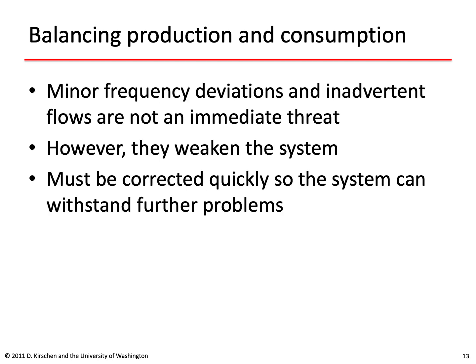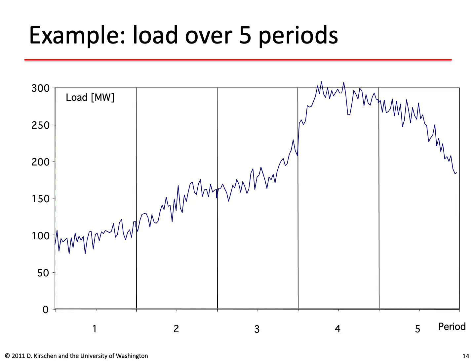Now, minor frequency deviations and minor inadvertent flows are not an immediate threat. However, they weaken the system, and therefore they must be corrected quickly so the system can withstand further problems. Let's take an example to see how all this might work.